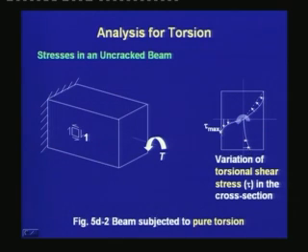The relative values of these two values and the two sides depend on the ratio of the two sides. If we go along a diagonal, we will observe that there is no shear stress at the corner. Thus, the maximum shear stress that occurs in the cross section is at the mid depth of the longer side.